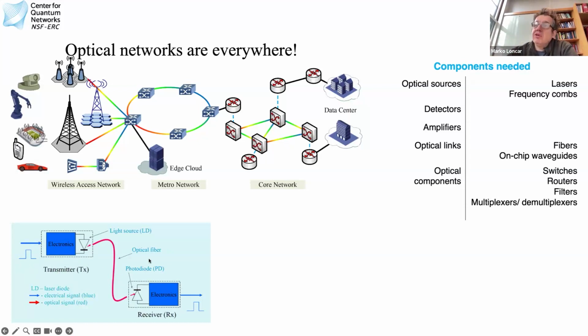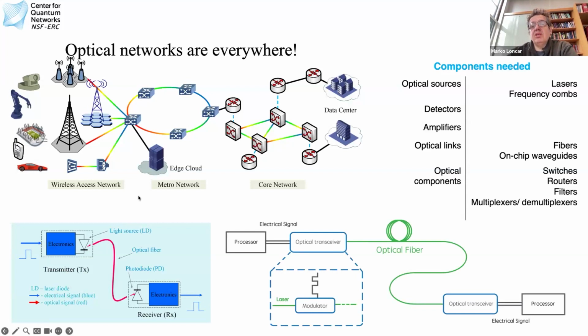The problem with this approach, where you directly modulate a laser diode, just for the sake of completeness, is that the speed with which you can do it is limited by the semiconductor physics of the laser diode. So you cannot go very, very fast, which is why most modern communication systems that rely on very high data rates, exceeding maybe several gigabaud, rely on externally modulated optical signals.